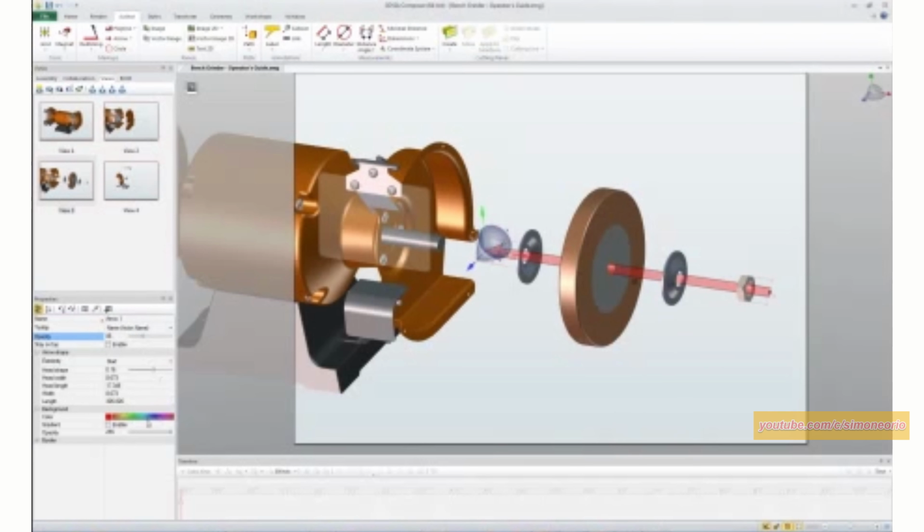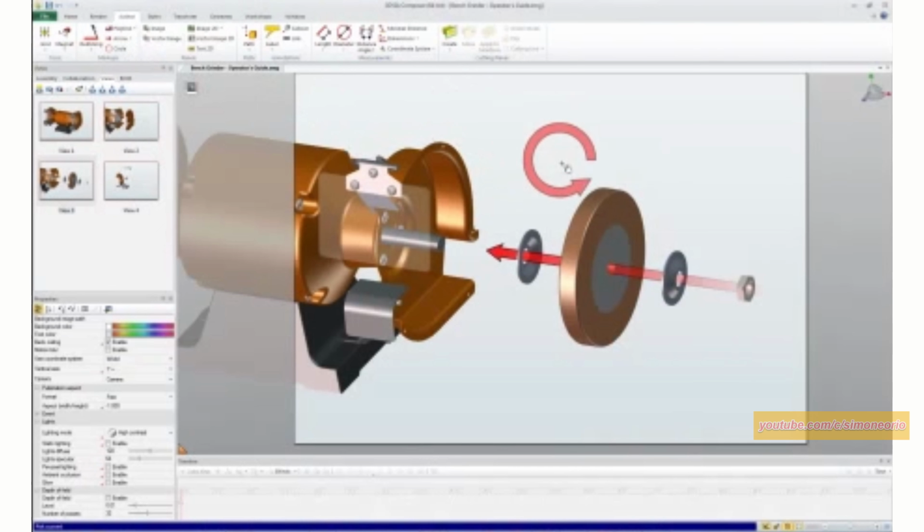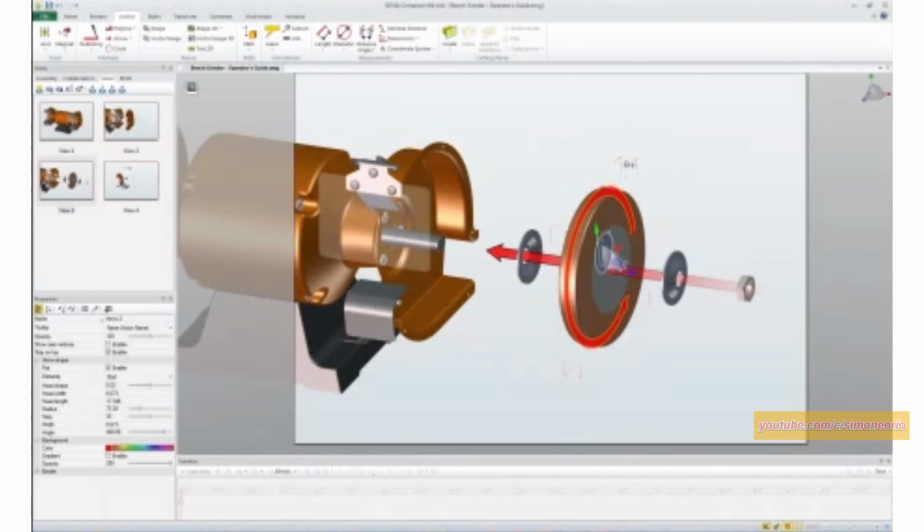And a really nice feature that I like is over here called gradient, where you can make it fade out. Brighten that up just a little bit, where you can make it start from a fade and get really solid by the time it hits the end. Another really cool arrow available, the circular arrow. Just a couple of many different types of tools that Composer gives you to allow you the ability to really create some nice instruction manuals.